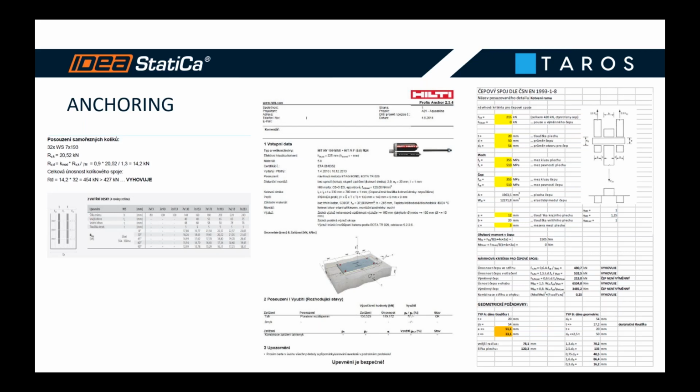We will show you. So going back to my original design, I used a couple of spreadsheets. On the right, you can see a snip from my spreadsheet for pin design. I also used some spreadsheets for the calculation of the plates, like plate in bending, plate in compression, just calculating the stresses. It wasn't even a part of the document because it's just small, simple tools.